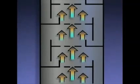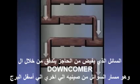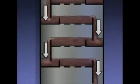The openings in the trays allow vapors to rise through the trays on their way up the tower. Each tray is also designed to hold liquid. Dams or weirs on each tray allow liquid to build up on the tray. Liquid that overflows the weirs flows into downcomers. The downcomers channel the liquid from tray to tray down the tower.